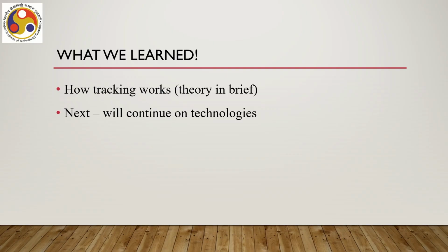Instead, we use cheap sensors, but through the calibration stage we transform their values to the values of highly accurate sensors through some mathematical manipulation. To determine that mathematical expression, we need a set of data samples from both the sensors, with which we are calibrating, or our underlying assumption about the accurate sensor.